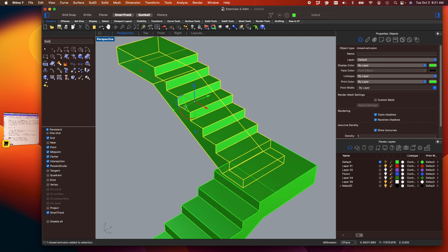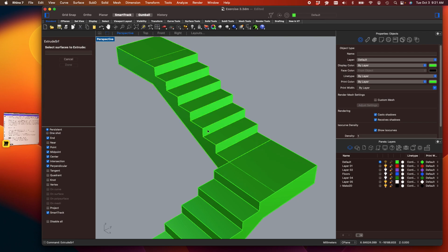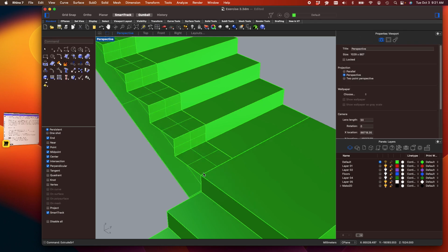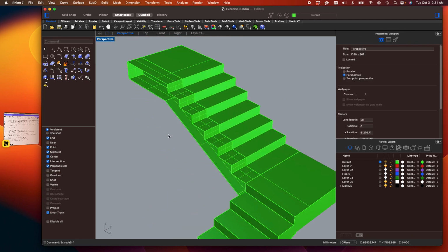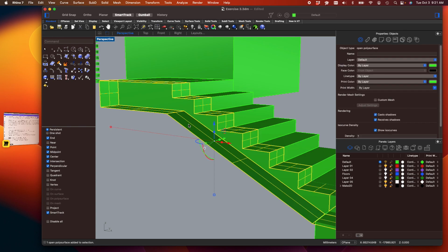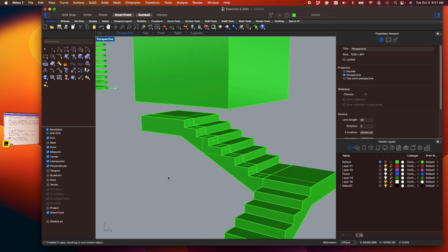So I can extrude also the face or surface, right? So I can select that surface, select OK and then basically go, well, I need it to be a little bit longer. It does make a separate piece and it leaves it open. So I might need to close it. I can cap it, right? Some people use it as a positive term, they say that's cap too. Anyway, it can be used both ways, just in case you were wondering.